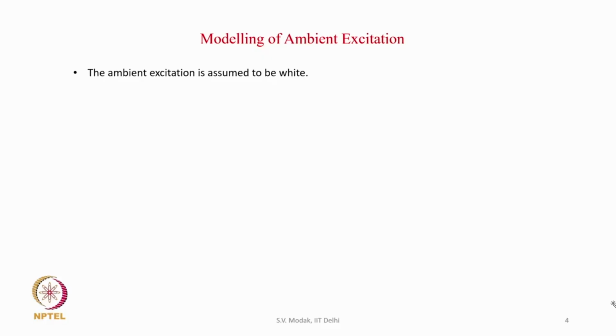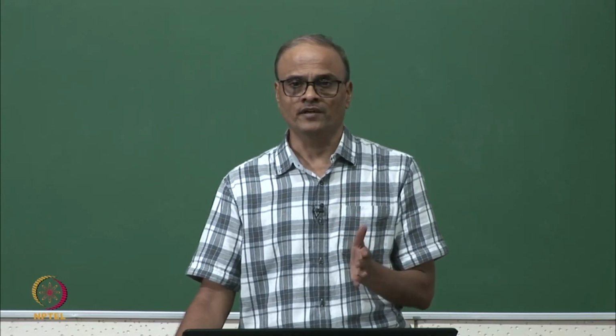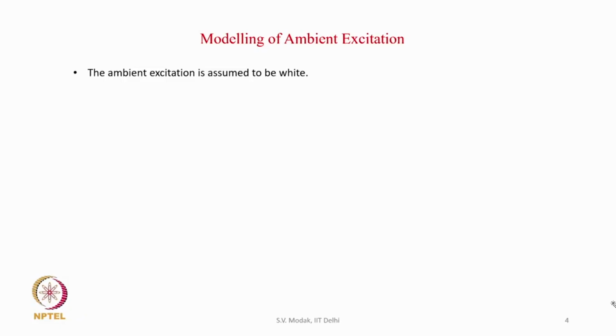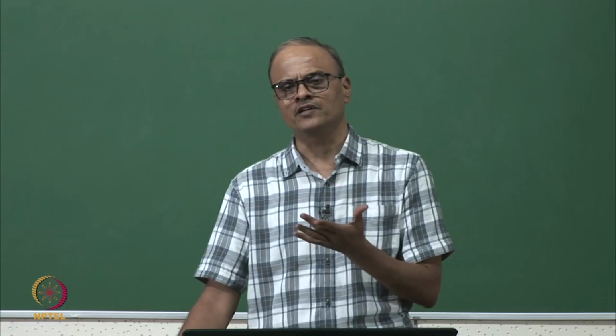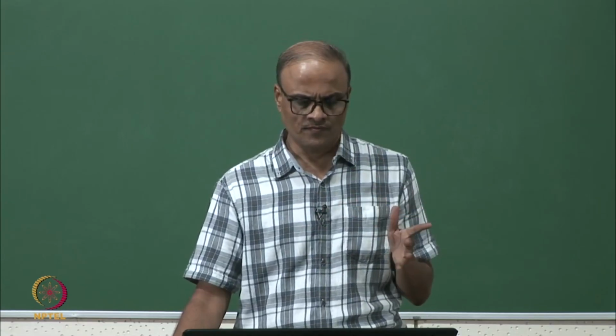The ambient excitation is assumed to be white in operational modal analysis. So, operational modal analysis assumes that the random excitation which is acting on the structures, the natural excitation, is white, right, and we know that the white signal has power spectral density which is flat over the whole frequency range. So, it excites the whole frequency range.